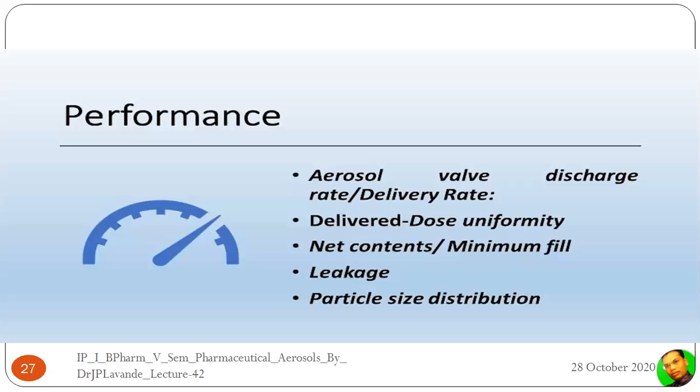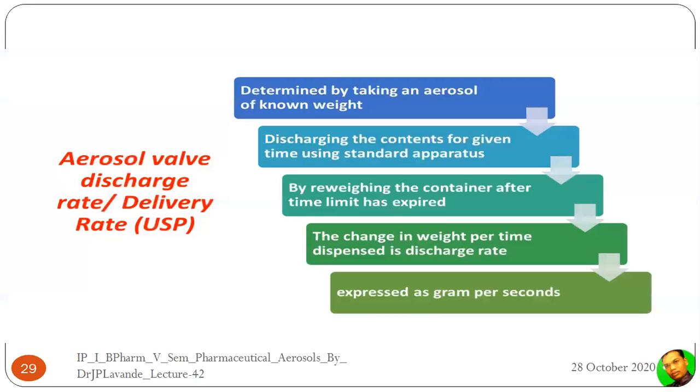Next is the performance. So the performance is in the form of the aerosol valve discharge rate, the delivery rate, the delivered dose uniformity, net content, minimum fill, leakage, and the particle size distribution. So these tests are to be performed in order to evaluate the aerosols.